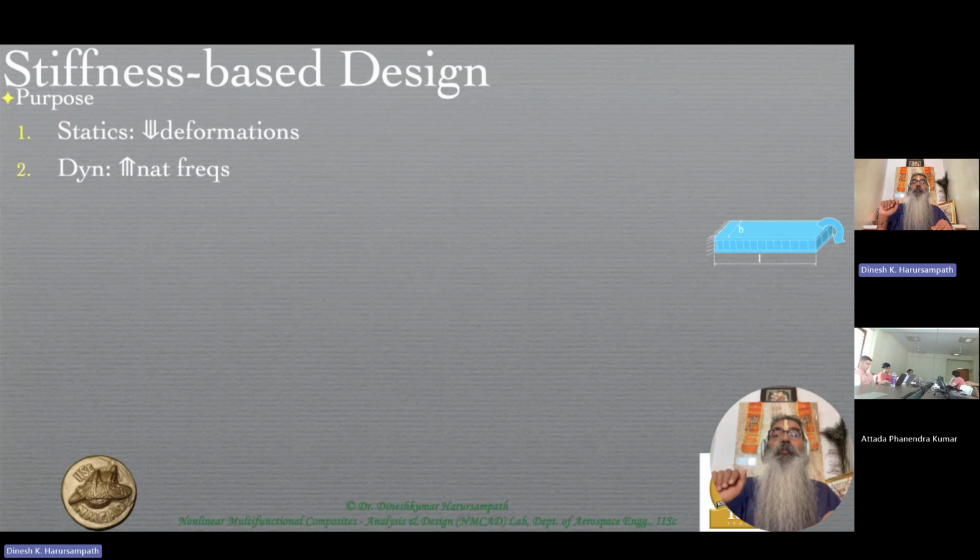And when they do that, let's say we are increasing the angle of attack and we are still below stall for the airfoil which is used. So essentially, all of them are lifting up, which means that they are all bending upwards. When they are bending upwards, the cone angle increases, and the overall lift increases, and the helicopter is able to climb upwards. In other words, able to accelerate upwards, and therefore it can go up. If you're decreasing the pitch, then the cone angle reduces and the helicopter comes down, right? So that's as far as the collective pitch is concerned.